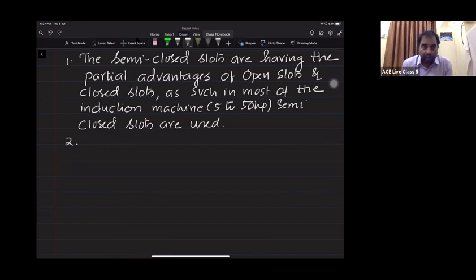We are going to see in the coming days that even though a three-phase induction motor is a self-starting motor, we need a starter. That starter is not for starting or turning the motor, but to limit the high starting currents. We will see starting methods as a separate topic for 4 to 5 hours, and there we'll see why we need a starter.